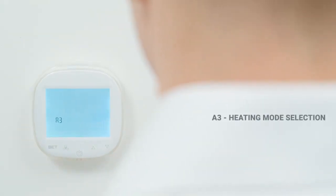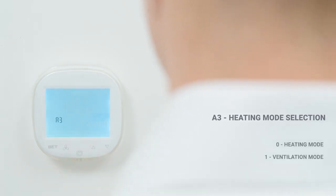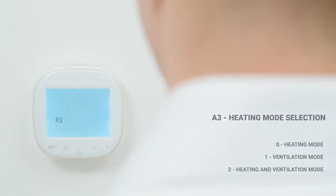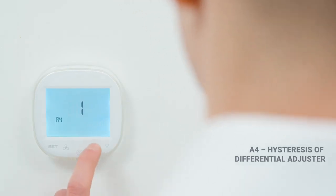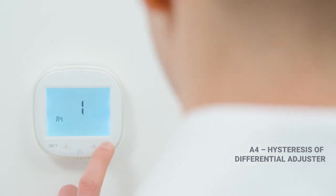Function A3: heating mode selection. Value 0 means heating mode, value 1 means ventilation mode, value 2 means heating plus ventilation mode. Function A4: controller hysteresis setting. This is the difference between the set point temperature and the room temperature followed by switching on the device.